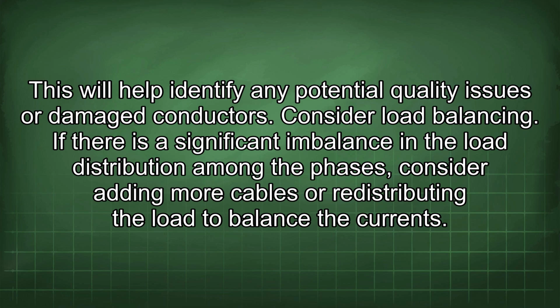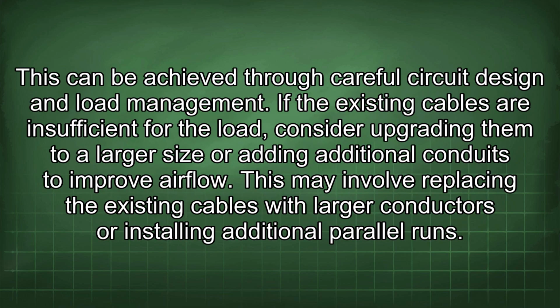Consider load balancing. If there is a significant imbalance in the load distribution among the phases, consider adding more cables or redistributing the load to balance the currents. This can be achieved through careful circuit design and load management.